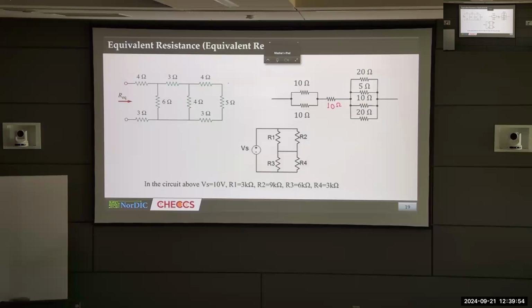Okay, so let me give you the brief overview. See these 4 ohms, these 5 ohms, and these 3 ohms. They are in series. Can you see that? After the 4 ohm, 5 ohm, then a 3 ohm are connected. So we can just replace these 3 resistances by one single resistance of how many ohms? 4 plus 5 plus 3, right? Any confusion in the question? So what we are doing is we are reducing little by little.